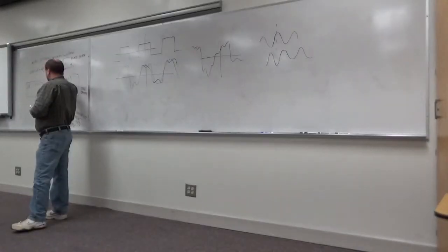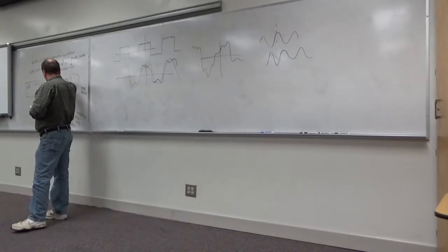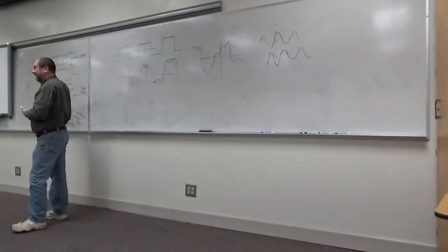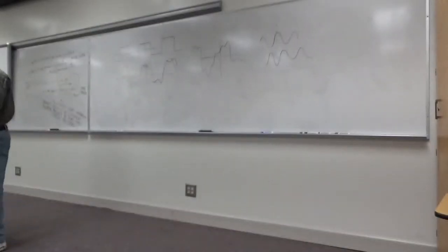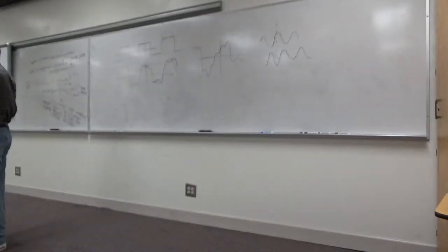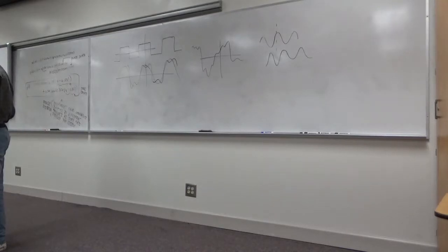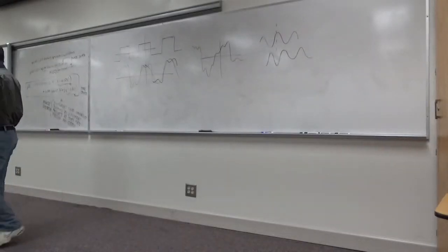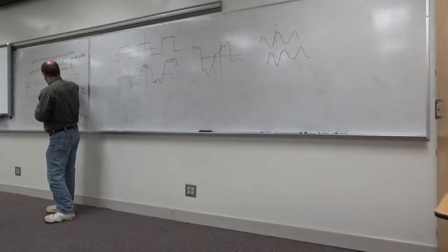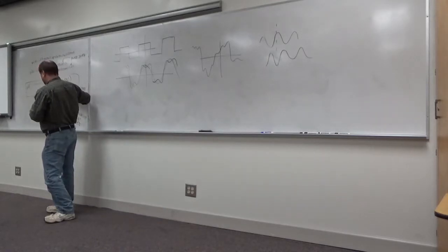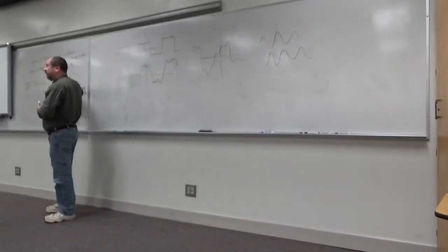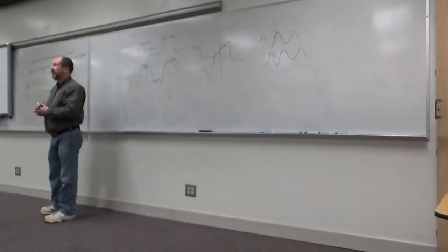I delayed one frequency component by this, and I delayed the other one by something else. If they get delayed by different amounts, it's what's called phase distortion. Okay? Now, I'm going to come back to that maybe next week, but I'm just introducing it. I want you to know what it means now. And that particular example shows it. This phase delay turns into a time delay, and now the phase is not the issue, it's the time delay should be the same for all of them if it's going to have no phase distortion.